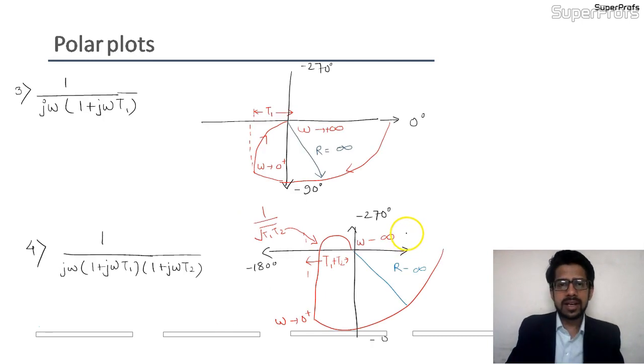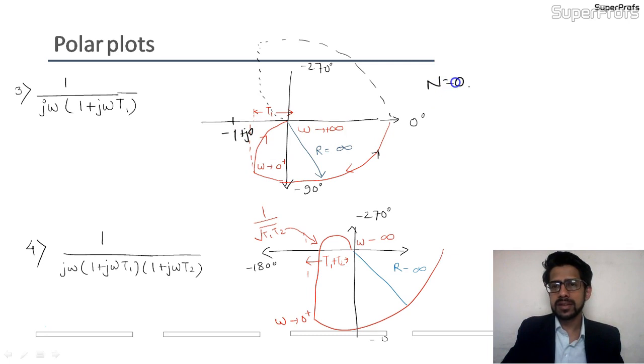Okay, let us look at different figures for this particular function. If you have such a contour, if you recreate the Nyquist contour, you get such a figure, and for a different arrow on the opposite side, still here the -1 plus j0 point is not encircled. Again, n is equal to 0. For poles lying completely on left hand side of the s plane, this is the pole on origin which is not covered by the Nyquist plot, so n is equal to 0 again.